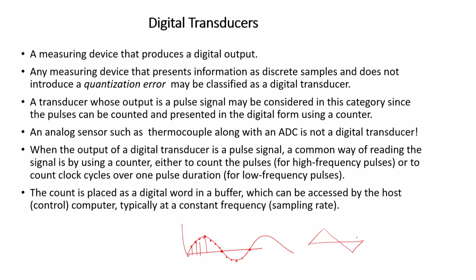You get at least some periodicity, but still that would not reveal the true picture. If you get more numbers in between these, then you can gradually build up that no, it is not a linear variation, it is a nonlinear variation, and similar like that. Okay. So, that is the quantization error that you have to avoid with the help of the sampling points. So, these are certain points that you need to keep in your mind from the analog to digital conversion